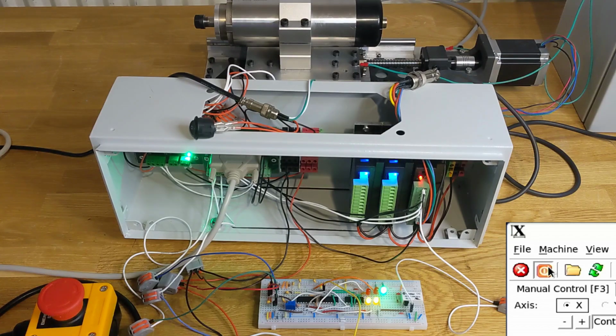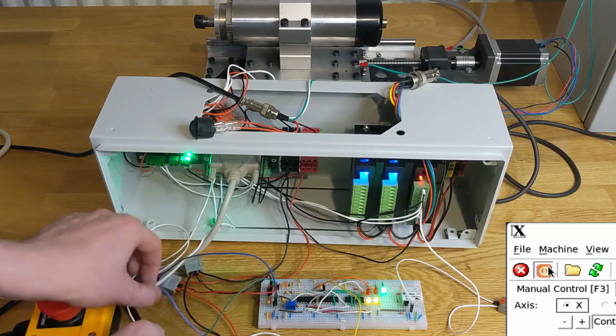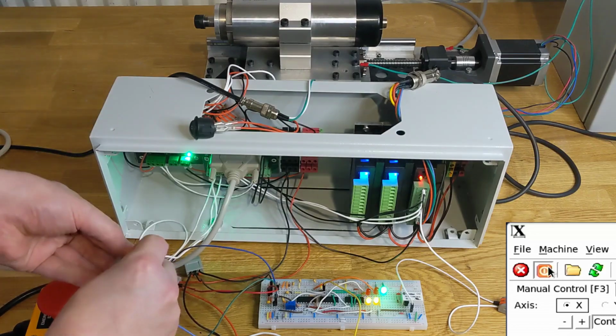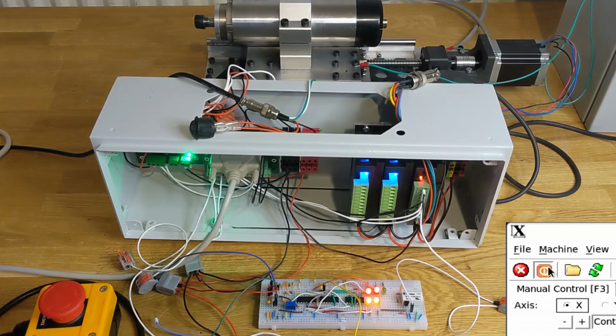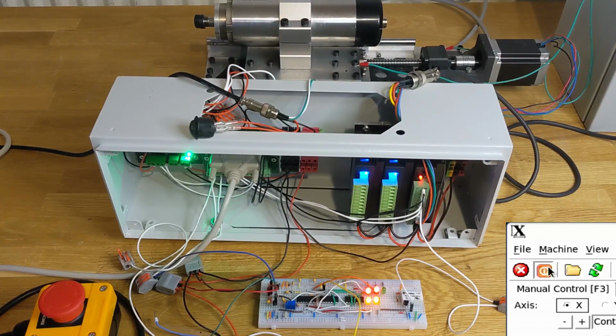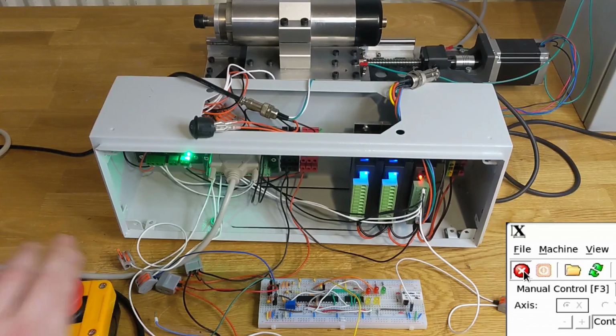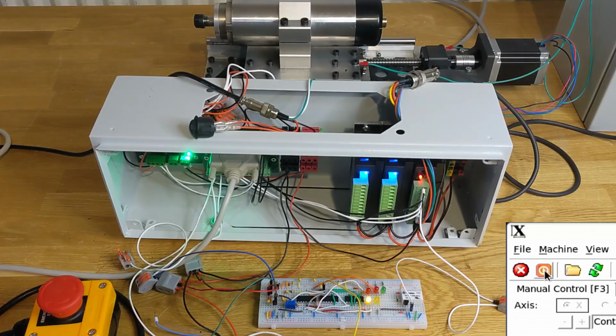Let's check what happens when we don't send the e-stop signal to LinuxCNC but only to the safety module. I'm disconnecting the e-stop switch from the e-stop input on the parallel port. Now when the e-stop button is pressed, the relay still switches off and depowers the motor drivers, but LinuxCNC doesn't know about it, so it's still sending the charge pump and enable state, and our lockout mode is active. To get the relay turned back on, we need to manually e-stop in the UI, and now the lockup is cleared and we can restart the machine normally.